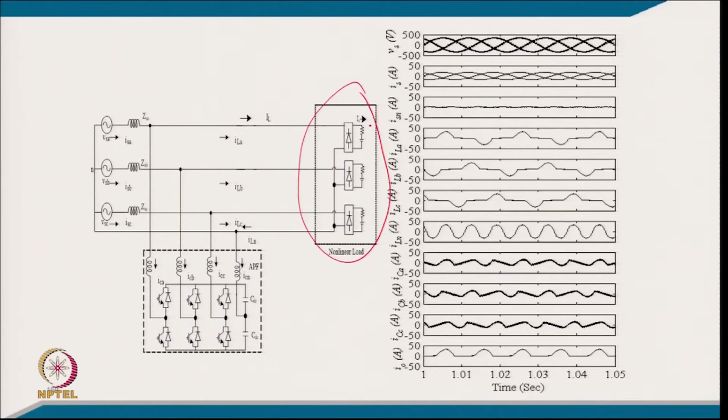So, this is the system that we have, a battery charging load for all 3 phases, equal, with the 2 ohm resistance in series, and this is the 4-wire shunt active filter, where the neutral is connected with the midpoint of the capacitor. So, after designing and simulation, these are the 3-phase voltage, 3-phase current, and neutral current of supply, which is made 0, and these are the 3-phase load current and neutral current of the load, and the 3 shunt active filter currents, and typically the load current.